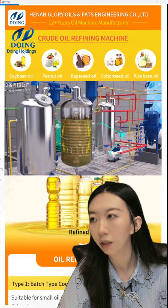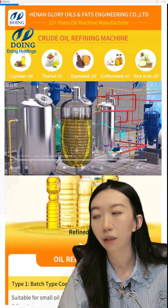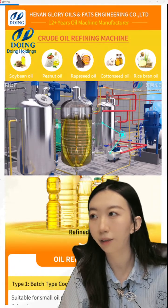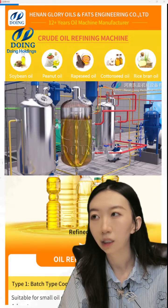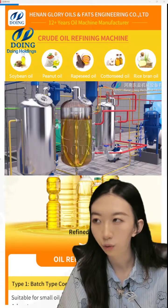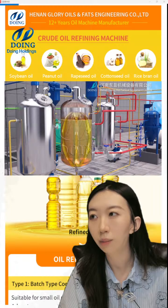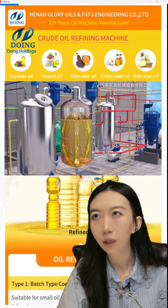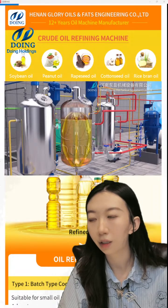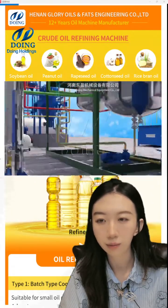And then the high temperature steam enters the deodorization tank to heat the decolorized oil. The decolorized oil will be heated to 260 degrees and boiled for 4 hours.